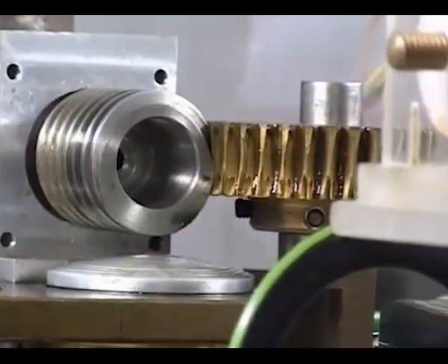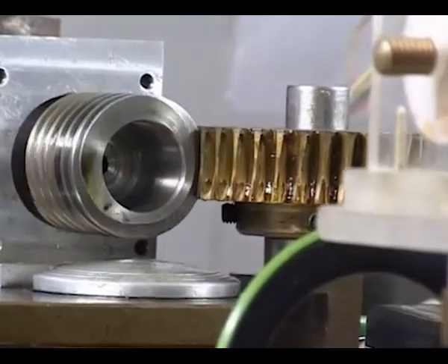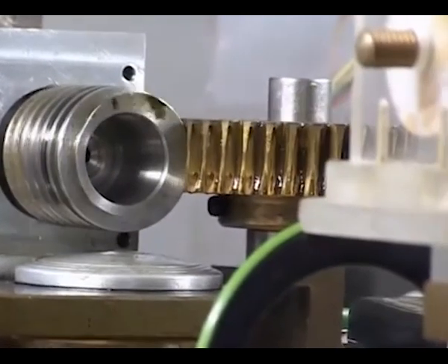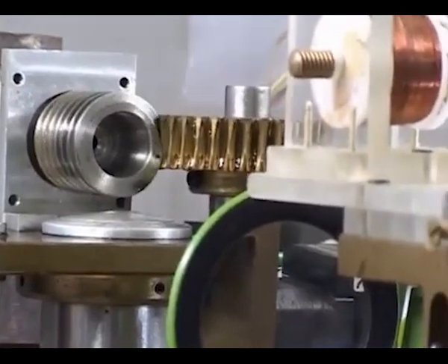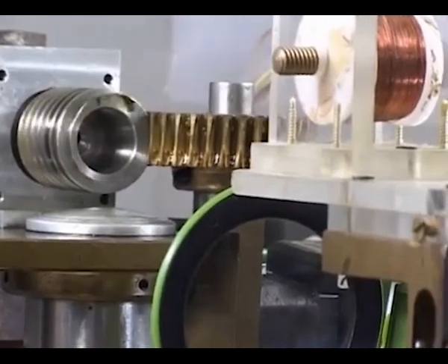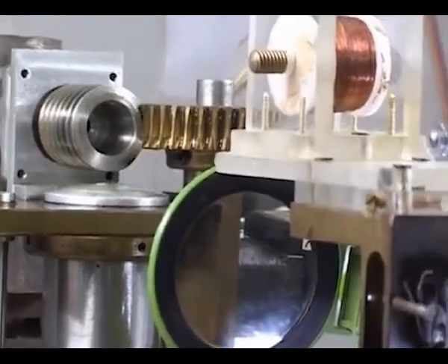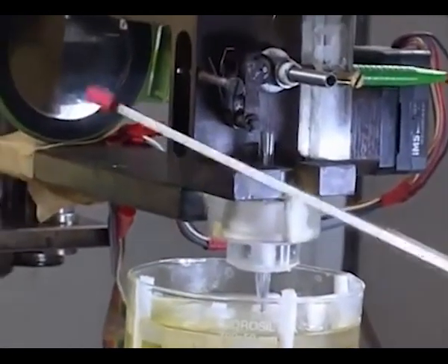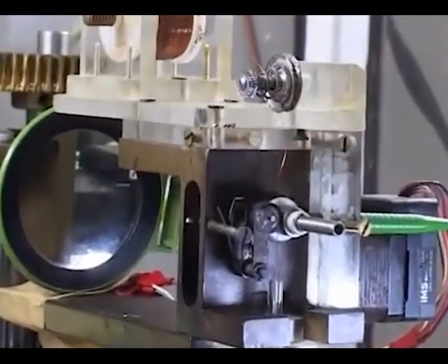One can see that the motor is moving in the opposite direction, and that the Z axis is taking this Z assembly to the lower position. The accuracy of this is 50 micrometers per pulse. So we can set the gap between the tool and the workpiece by taking the Z axis assembly and by adjusting the tool feed also.